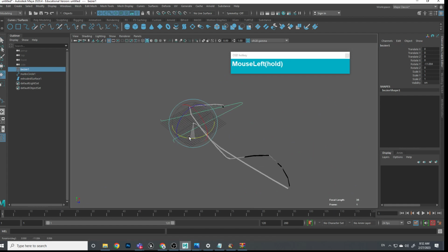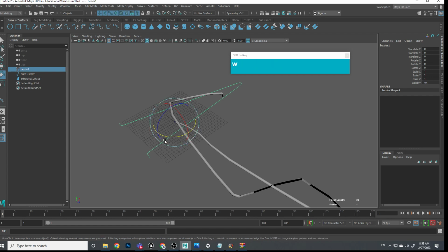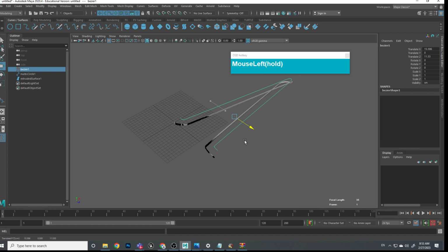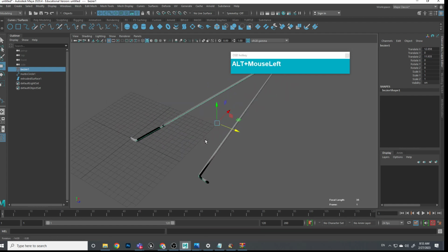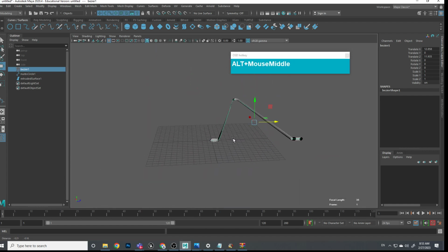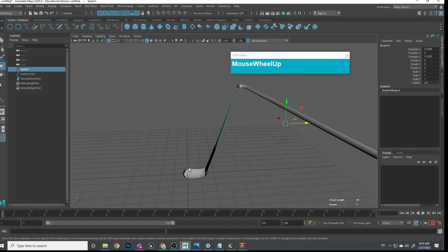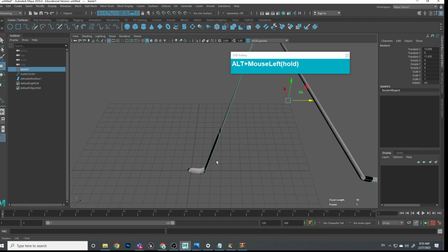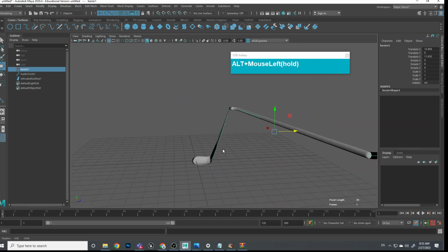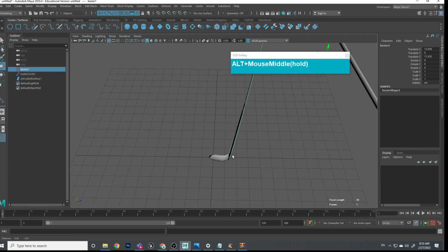If I rotate this curve or move it around, right now the beginning and the end is in a very incorrect location. So I'm trying to move it so that one end of the curve is at the correct position. Now you can see that the curve appears to be flat. The beginning of the point and the start of the profile must be in the same place. So that's why we have this phenomenon going on. And right now you can see that the extrusion is not working because our profile needs to be rotated.